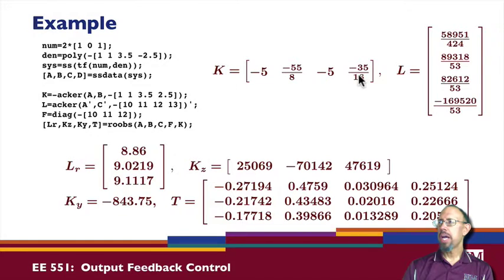So using a state feedback, and if we use a full order observer, then we use this observer gain, and we get the desired eigenvalues. If now we choose F to be a diagonal matrix with these eigenvalues, we can use this command that I've created. You can find this M file on the Canvas site or the website.